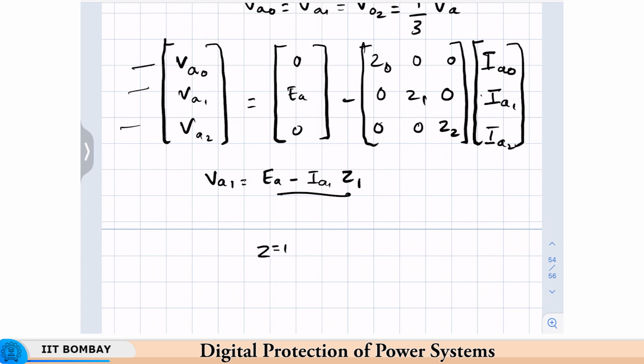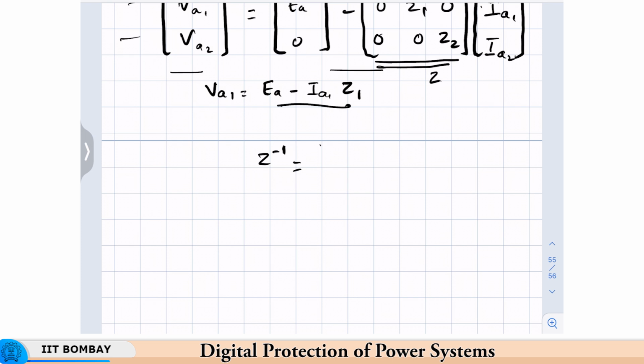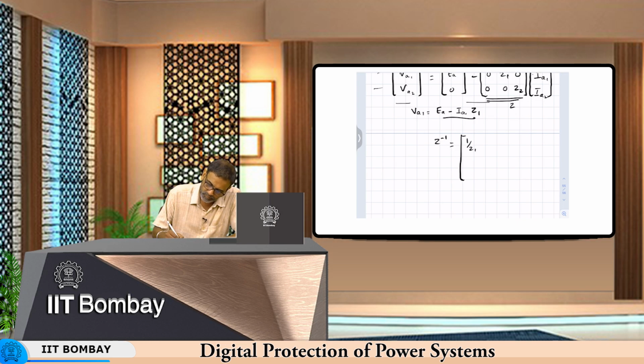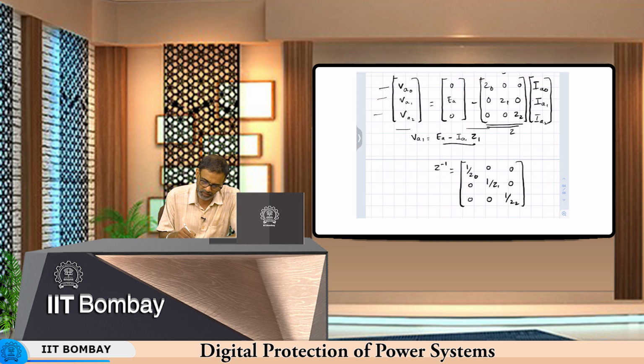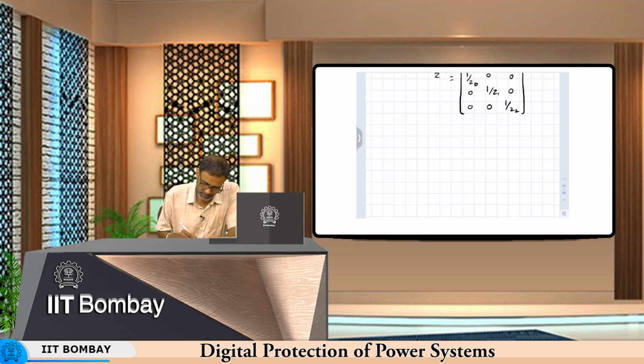Now, what is Z inverse? Since this is a diagonal matrix, I am sorry, it is not Z equal to 1, it is Z inverse. So, we will pre-multiply both sides of this matrix equation by Z inverse. If we consider this matrix as Z, since it is a diagonal matrix, Z inverse is quite simple: 1 upon Z0, 1 upon Z1, 1 upon Z2. The first step is substituting EA minus IA1 Z1 here for all the three values, since they are equal, and then pre-multiplying both sides of the above equation by Z inverse.